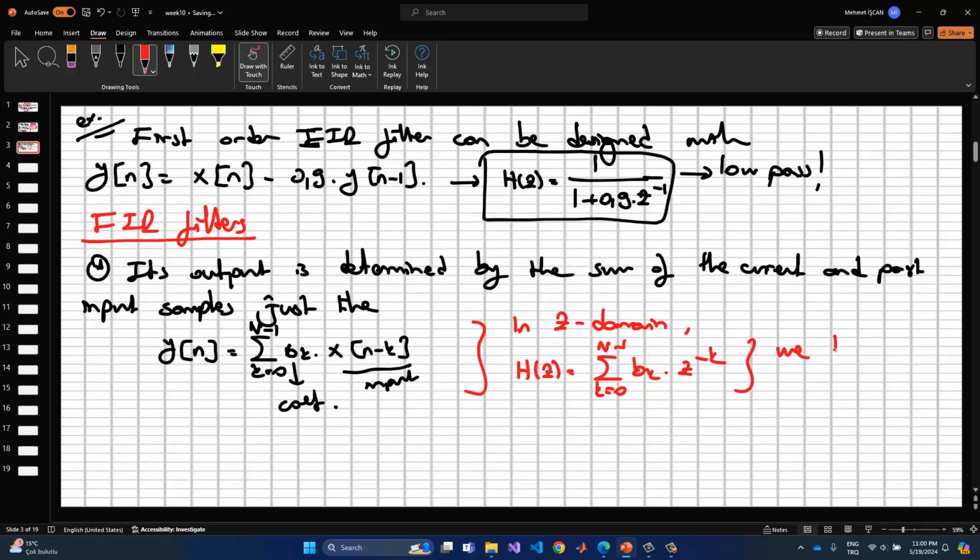In this case we don't need to check the poles, because if the input is bounded, this yields a bounded signal, since it's the open loop response. In the previous case we had the closed loop response, or feedback, which may continue to grow or decrease with respect to the input signals. But in the FIR filter we don't have any stability issues.